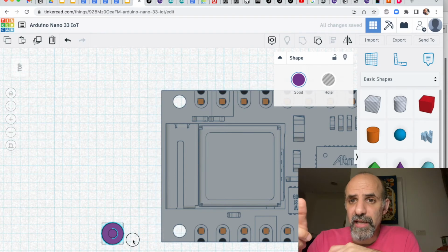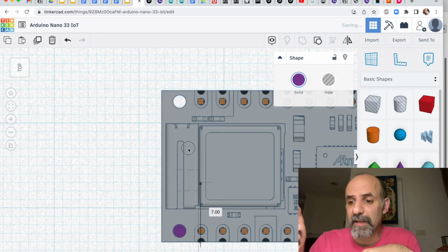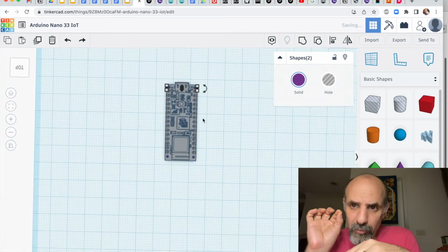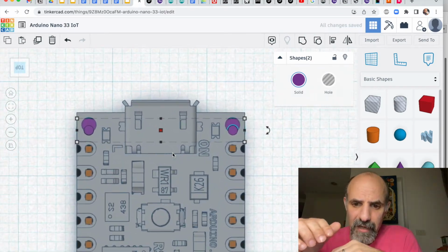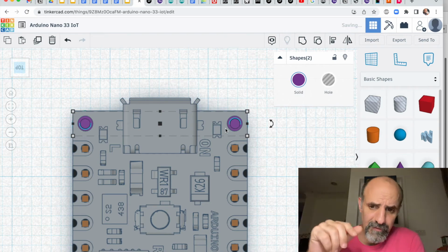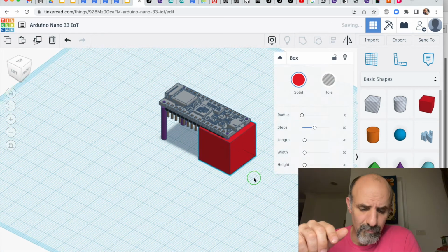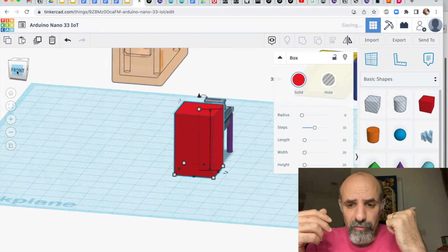And I've been using the 1 millimeter grid, but for something like this, it doesn't really fit. So I need to get out of the grid and be able to put a concentric circle one inside of the other. So once I have that, I can also drag things, pressing Option, and that will duplicate them. Or you can also Control C, Control V.